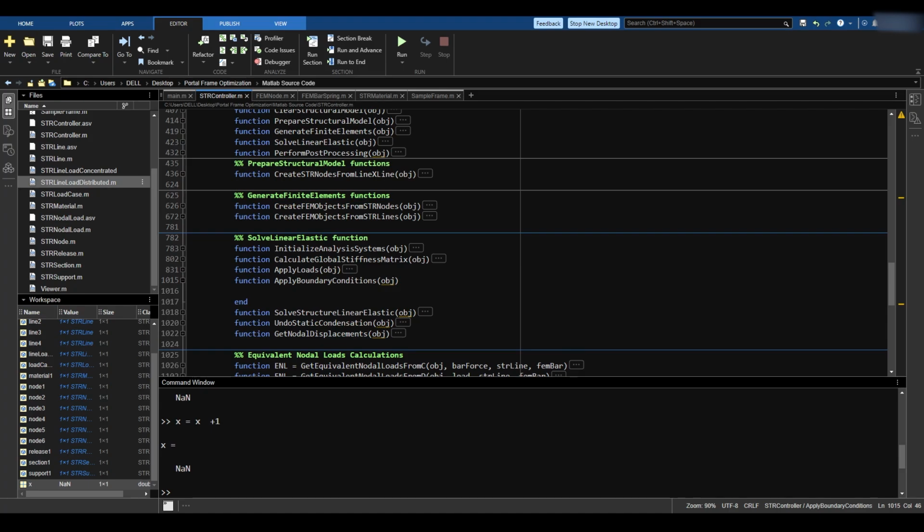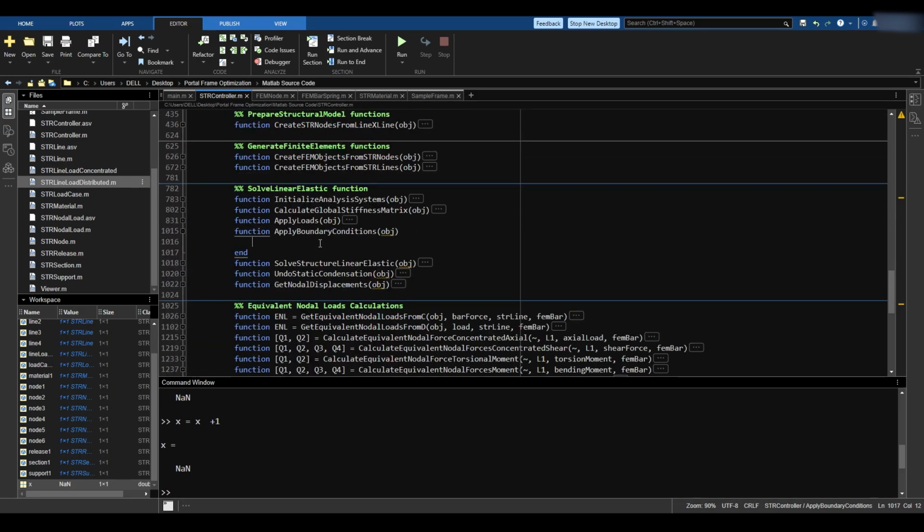So we need to find K11, K12, K21, K22, and so on, based on whether a certain degree of freedom is boundary conditioned or not. So the apply boundary condition not only applies the boundary condition, but it also subdivides the matrix into the four pieces it needs to be in order for us to solve it. You can double check equation 2.5.13 in Daniel L. Logan's book, page 42, chapter 2, to check out the equations I'm talking about.